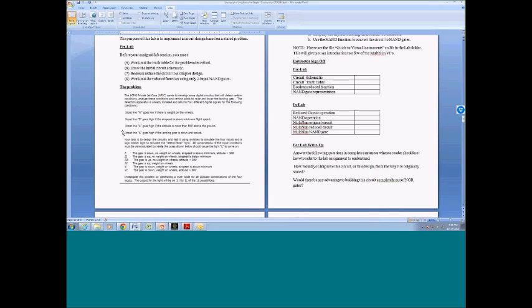Once they've simplified this circuit, they wire it up and see if they get it to work. In addition to building it, I have them simulate it on Multisim, and that's where I also have them figure out the reduced circuit. They can do the Boolean reduction on Multisim, then put it in NAND gates, and see how that works from a software standpoint. And that works really well.